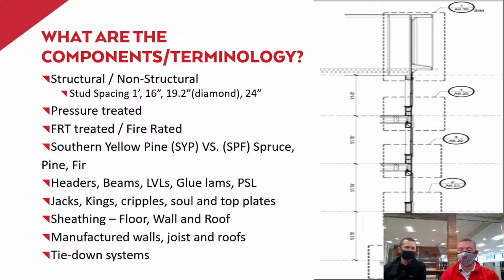When in doubt, question it. That's my best recommendation. If you're unsure that a stud or a sole plate or top plate is Southern Yellow Pine when it's supposed to be, get your carpenter involved and make sure that it is.